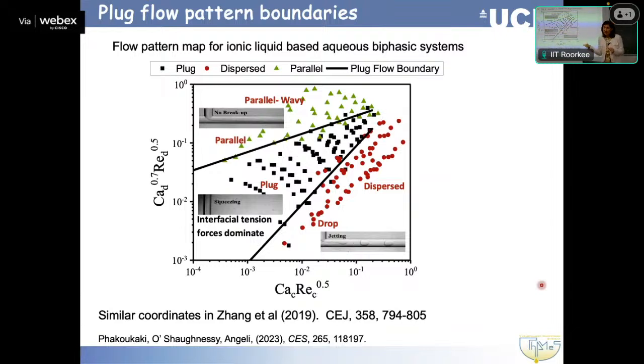And as I said, the other thing here, we have seen it a lot in the microchannels. I had a student that was trying to do plug flow with ionic liquid and water, and she could not get what the previous student had. We used the same channel diameter, the same channel properties. We should have thought, or she should have thought, but she was literally using different inlet sizes, the inlets that fit in the T-junction to actually give you the main channel. Which is trivial in a way. If you pay attention. If you don't know, then it can be missed in the design.